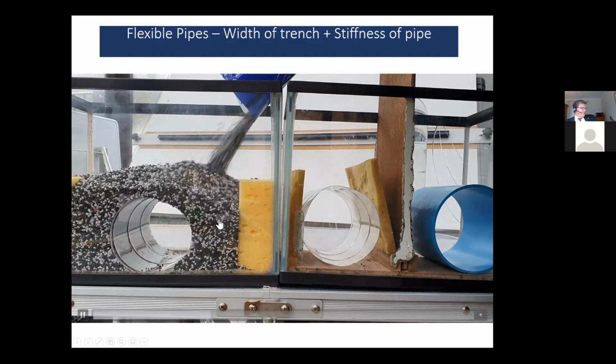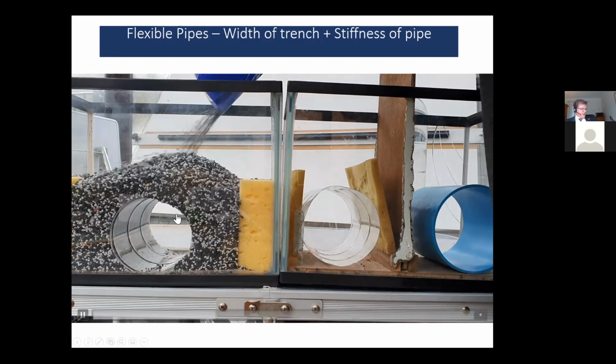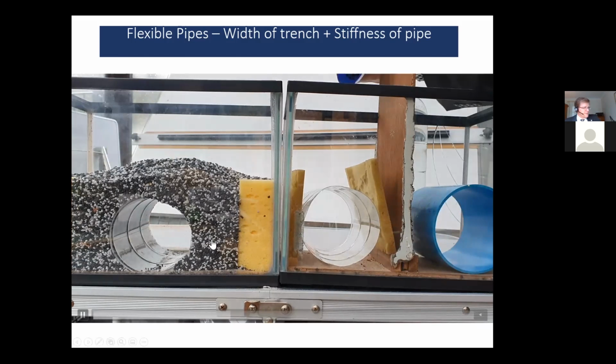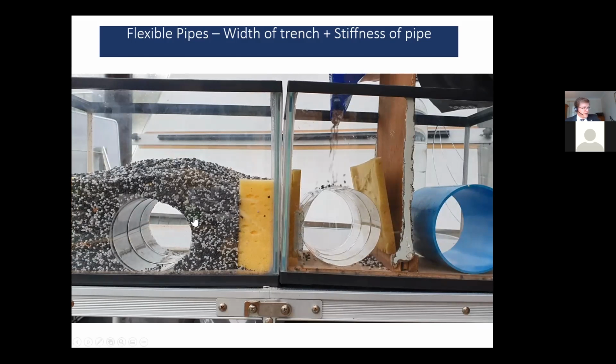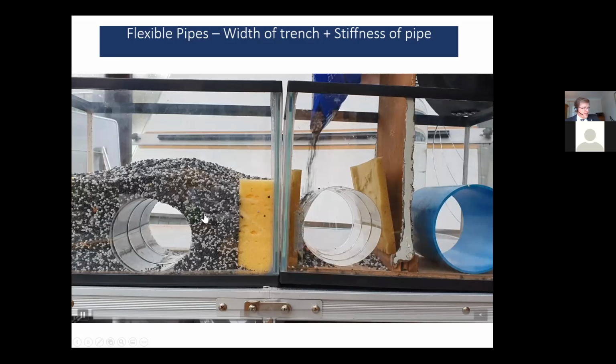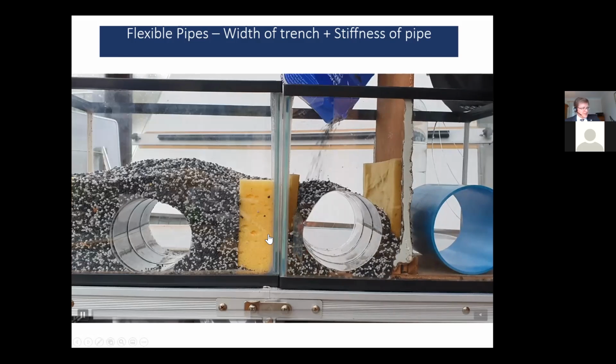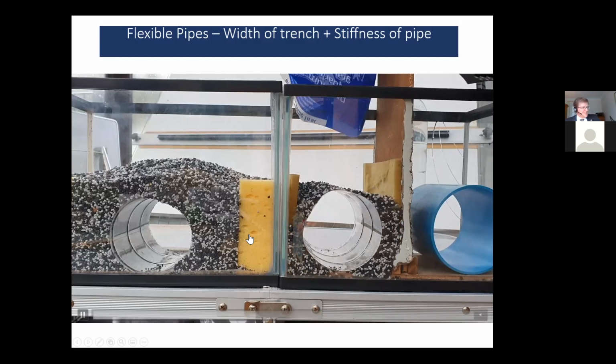We'll fill that up, and we're going to do the same. So these pipes are the same. The gravels, backfills are the same. The ground conditions are the same. The difference will be the width of the trench, and the one on the left being wider, so you have more of the good material before you get to the softer material. We'll add a little bit more into this, and then we're going to load them up.